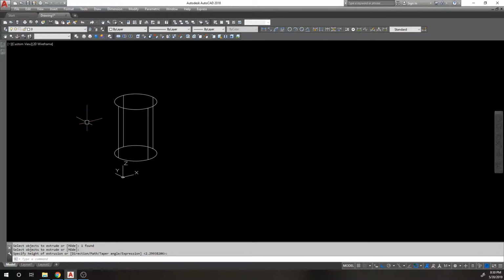Okay? And you'll notice that the lines look kind of funny. There's a setting that controls that. In fact, I'll go ahead and give you those settings right now to control those lines. One of the first settings you're going to want to enable is the display silhouette command. It's DISPSILH, and you set that to 1, and then regenerate afterwards by typing in RE or regen, either one. You'll see lines on the outside because it's displaying the silhouette edges of this cylinder.